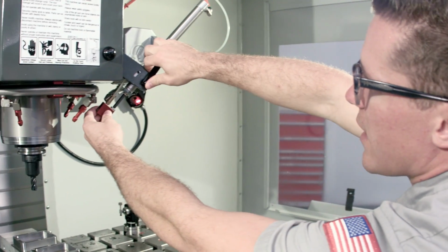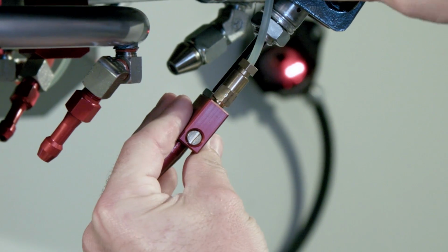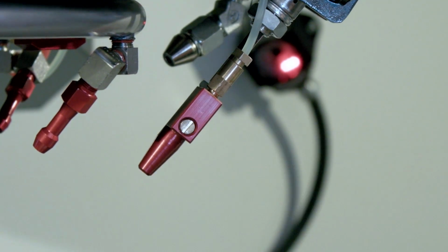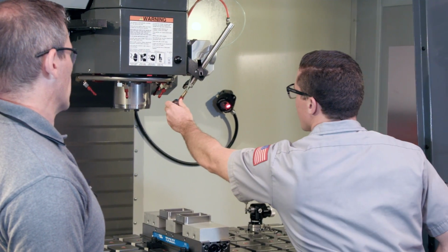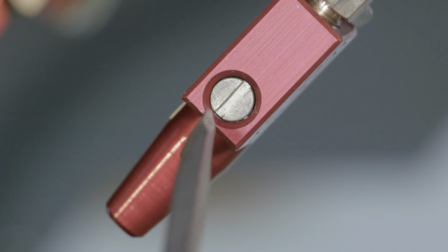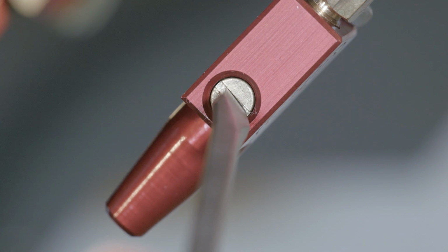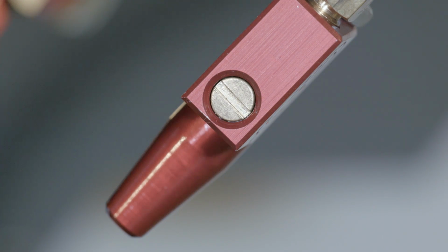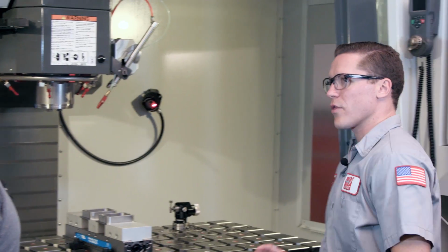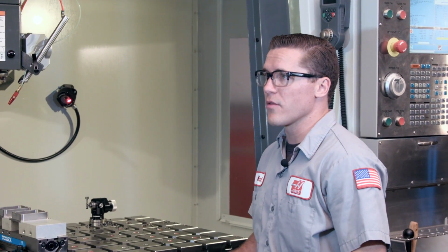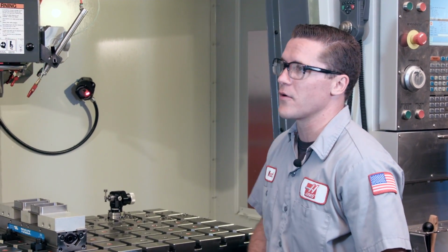So we're going to take and rotate the nozzle so that the adjustment screw is facing us. Now I'm going to rotate the screw clockwise until it sinks gently in place. Remember that this is our coarse adjustment. We'll take a look at our fine adjustment in a minute. With the screw closed, no oil is emitted, and it functions just like the auto air gun.